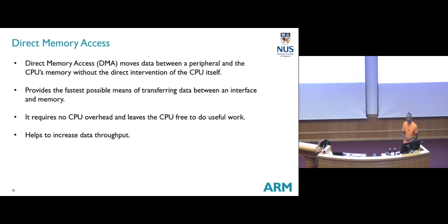Now just a few more slides on DMA, just to give you the idea. This idea of DMA is something that most microcontrollers have. Your KL25Z also has it. The idea is you want to be able to free up your processor for cases where you want to do a lot of large memory transfer. For example, if I give you 2 large chunks of array, let's say this is A and B, and let's say this is 1 gigabyte of data, and I want to copy 1 gigabyte of data from A to B.